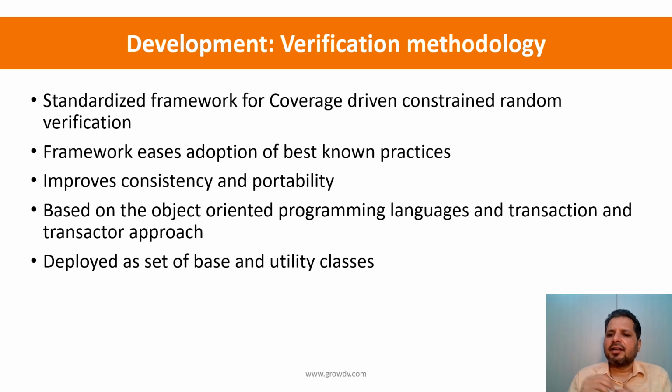Now if we buy a third party component, it will be much easier to integrate. And the point to note here is that all this is possible because UVM is built on top of SystemVerilog, which is an object oriented language. Because of the object oriented nature of it, we are able to build a methodology. Otherwise, building such a methodology, which is theory plus the deployment of theory in the form of base classes, is very hard if we have to do it only with Verilog, right?